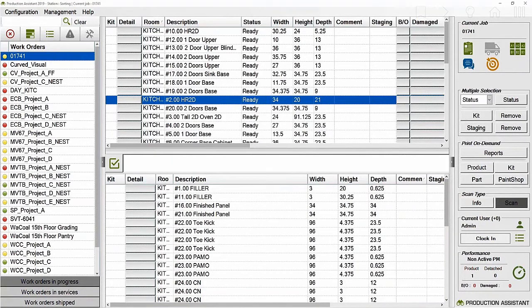Another example, really simple. I had a customer whose drawer boxes are 90% metal, with metal sides. So he only has a bottom and a back to cut on his CNC. But 70% of his issues with his CNC were coming from these backs that were always moving on the machine, from a lack of vacuum or that kind of thing. So what we decided is that we're not cutting the backs on this CNC anymore. He has long strips of backs waiting in his drawer department, and only the bottoms are being cut.